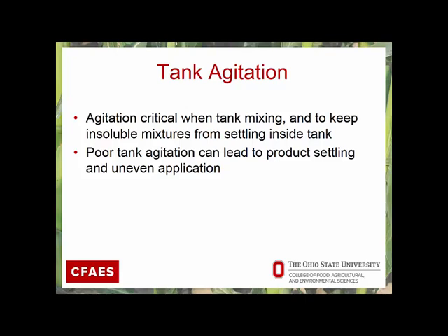Here again, poor tank agitation can lead to products settling out and even an uneven application. So why would it lead to an uneven application? It's because if you're pulling out the dilute solution, you're getting an under application, but if you're pulling out from where it's a sludge at the bottom of the tank, you could be putting on very high amounts, and this could lead to phytotoxicity and clogging of your equipment, etc.